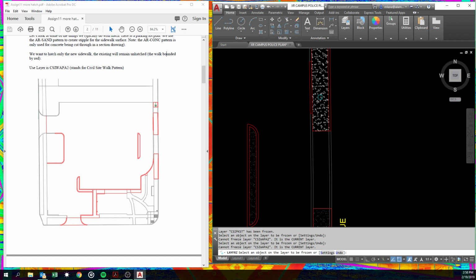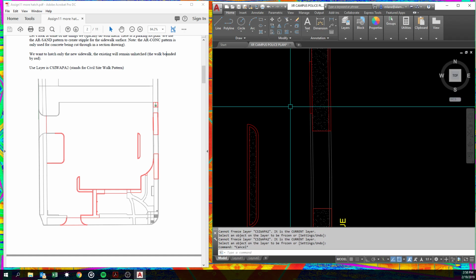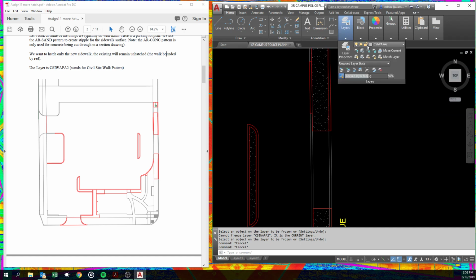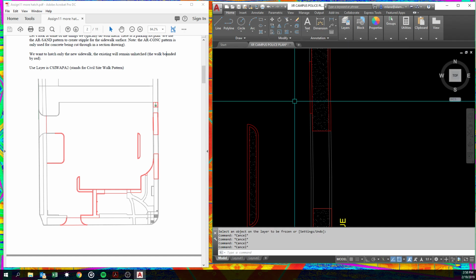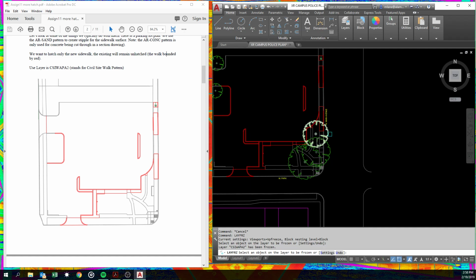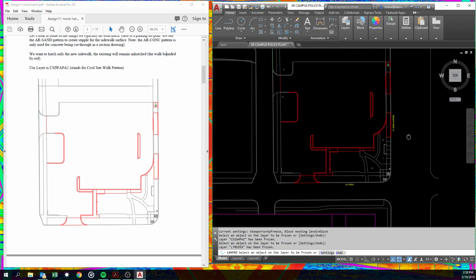And we're going to put this stuff in so y'all don't have it yet. Oh, that's my current layer. So we'll set, and I need to show you how to bring this up as a dialog box too. We'll make that current. Go back to lay freeze. And these are going to get in the way, so we don't want those. Don't really need the streets on either.